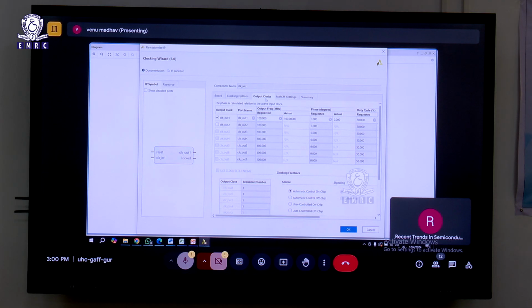So if you have given 3 clock wizards, it will consider that you require 3 clock wizards, and it will give you 3 clock wizards. It will not say, okay, use this clock wizard 3 times. That is not possible. It's not customization. The customization is only happening once 3 clock wizards are there: what is the MMCM or PLL that I have selected, which one should I pick, and what is the clock routing that I should do? That is the only customization that it is doing. It's not changing anything else. It's not changing the design at the core.